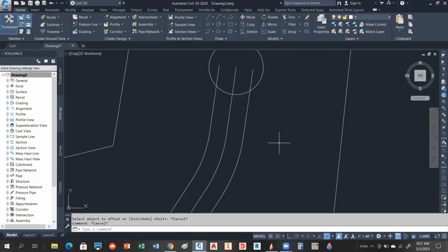Is everybody okay? Now, when you do that offset, is that geometry going to automatically connect those arc lengths? It will, because the way we drew them, it works perfectly. Now, if you have lines that are not tangent to your curves, you may have some weird irregularities going on. So that's a really good question. But in general, if you've drawn it correctly with tangent curves, you shouldn't have an issue.